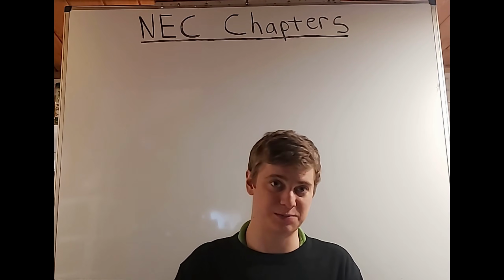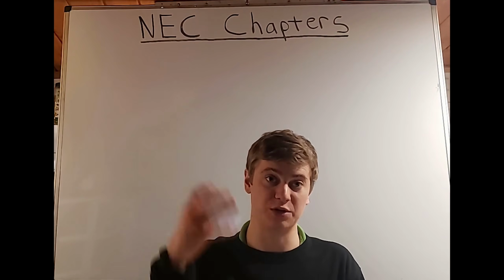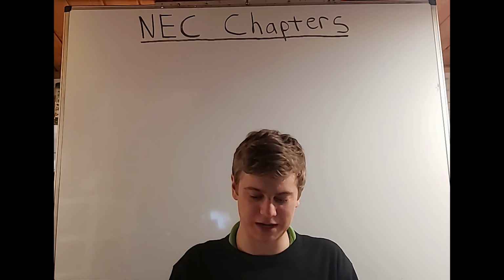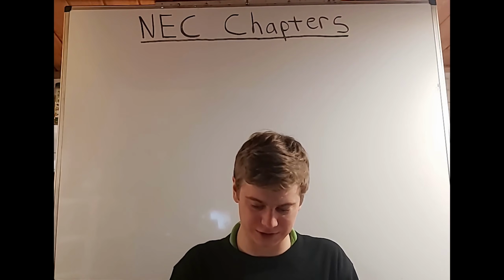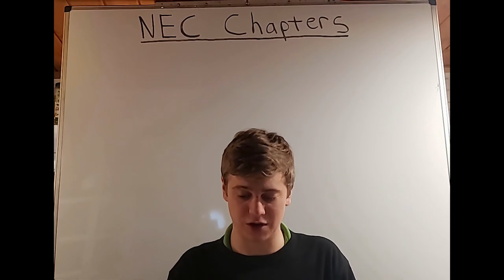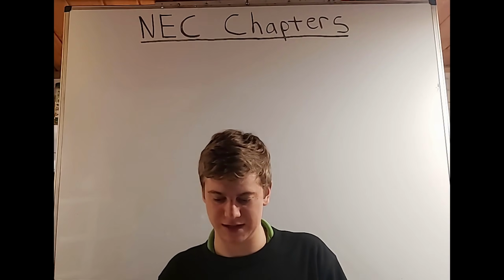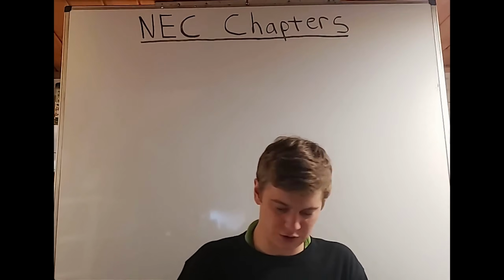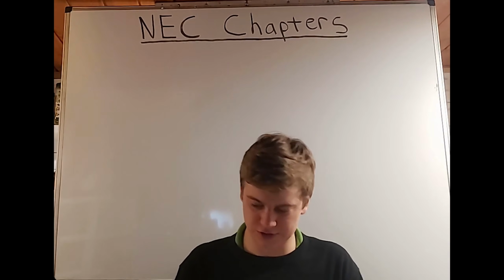You have certain specific locations for where you're burying conductors, and you have certain columns. Column 1, you have direct burial of cable or conductors. Column 2, you have rigid metal conduit or intermediate metal conduit. Column 3, you have non-metallic raceways listed for direct burial, and the list goes on. Article 310 is conductors for general wiring.